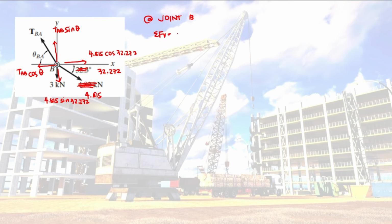Summation forces vertical is equal to 0, upward positive, and the other one, summation forces horizontal. So for vertical, we would have here TAB sine theta. Then we have minus 4.815 sine of 32.272. Then we have yung 3 kilonewton pa dito, minus 3. Then we don't have any other vertical forces. So this is equal to 0. So first equation, because we have two unknowns, yung TAB and yung theta natin.